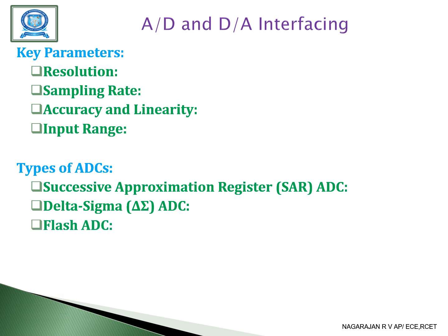The next type is a flash ADC, the fastest type of ADC, using parallel comparators to convert the signal in a single step. Flash ADCs are used in applications requiring extremely high speed such as a digital oscilloscope, but are limited by their higher power consumption and lower resolution.